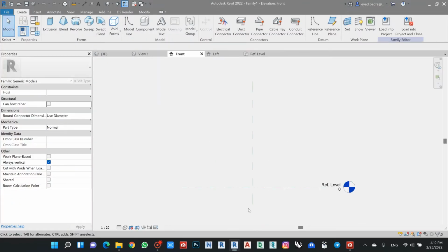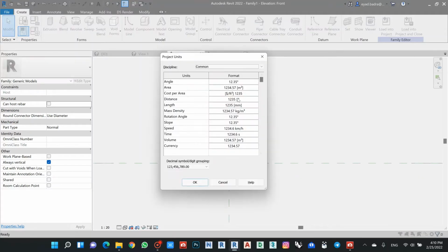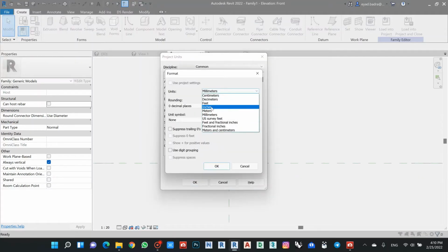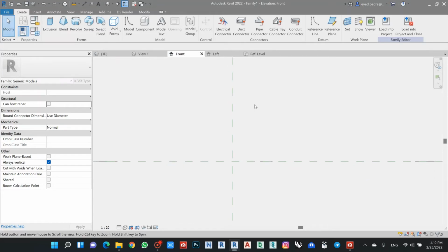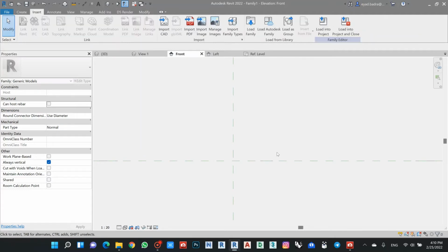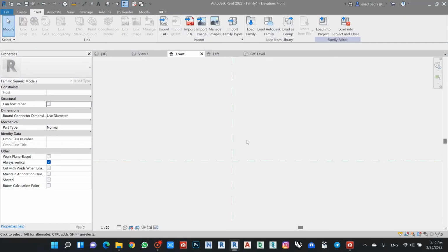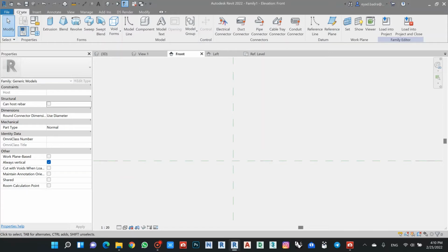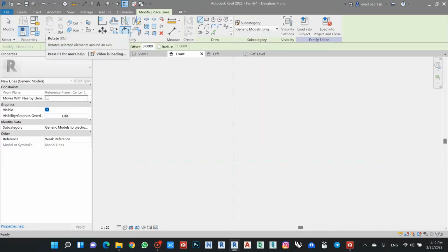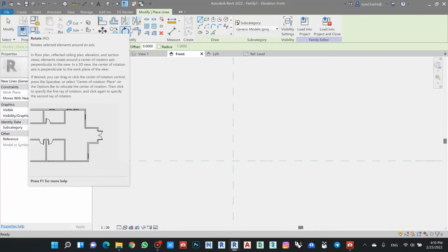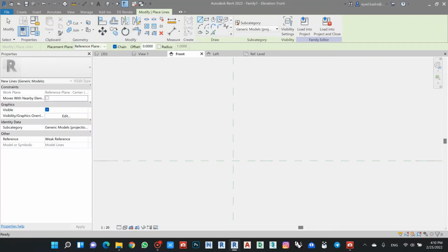The important thing is I go to the elevation, and from the elevation let's set the unit first to meters. Let's see, it's like a small circle with 2 rectangles, right and left. And we can make it double the radius that we use: 0.3, let's say for example 0.4, 0.5, let's say 0.5.